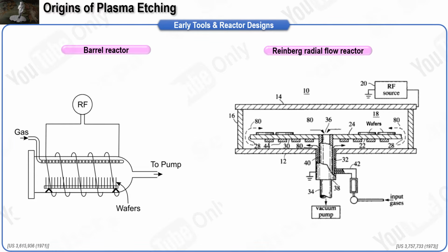The basic idea had roots in 19th-century induction experiments reported by Thomson, and it later converged to radio frequency operation that the industry standardized near 13.56 MHz. By 1971, Irving reported silicon etching in carbon tetrafluoride and documented gas plasma vapor etching methods. The push toward plasma came from a need to reduce wet chemicals and from the desire to reach hard films like silicon nitride and thermally grown oxide with cleaner profiles and better line edge preservation than wet etching could offer.